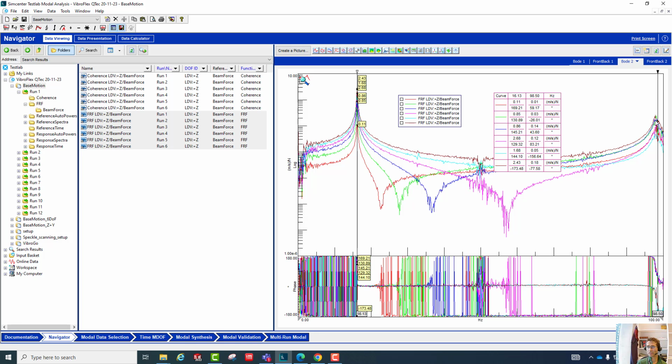That's where I get my first resonance, and the second frequency of interest is towards the upper frequency limit. I'd prefer that frequency to be a bit lower, I'd prefer my beam to be a bit longer, and then I'd have a lower frequency. But let's just focus on this frequency here, which we can do.